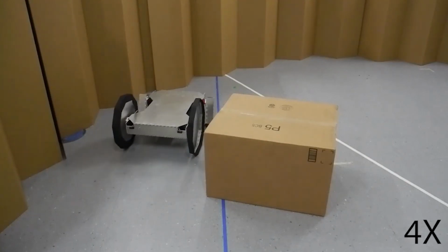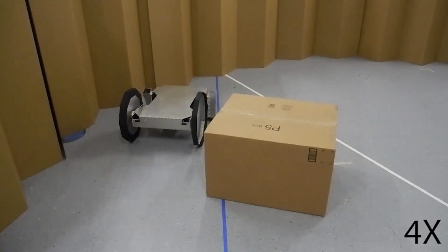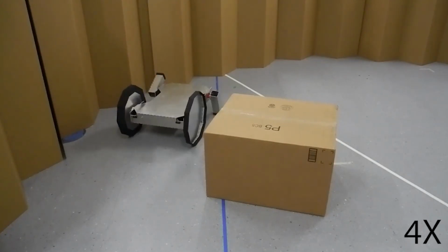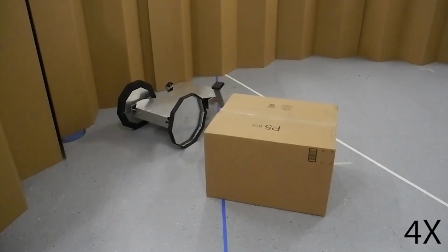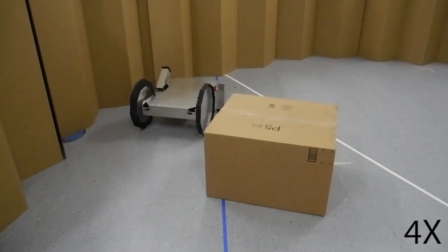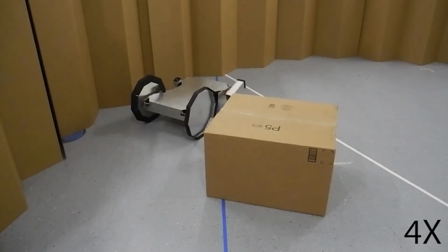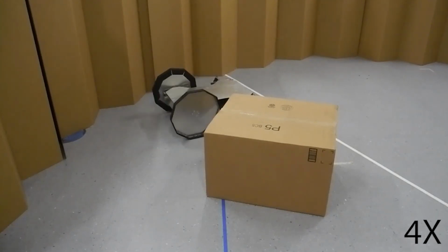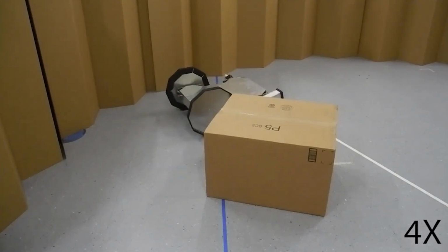We further instrumented the aluminum robot with 4 range sensors and some additional software that chose a forward or a left or right turning gait based on the sensor information. This allowed the robot to navigate an obstacle course of cardboard boxes and demonstrates the feasibility of building up high-level robot behaviors using the designs produced in our tool.